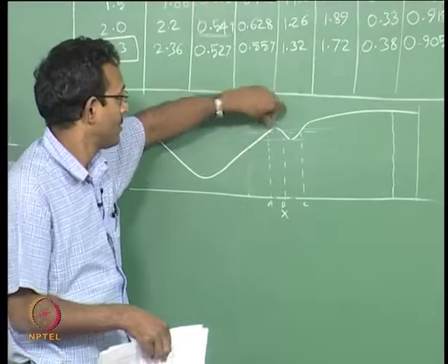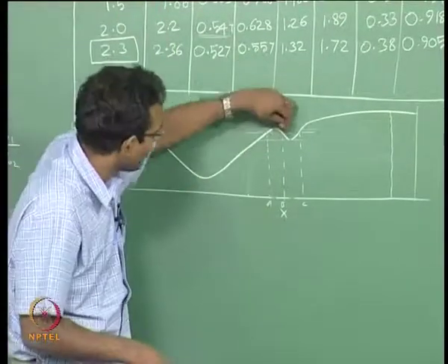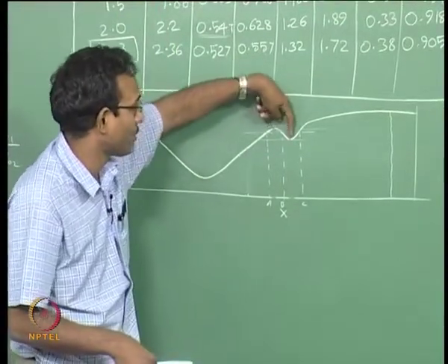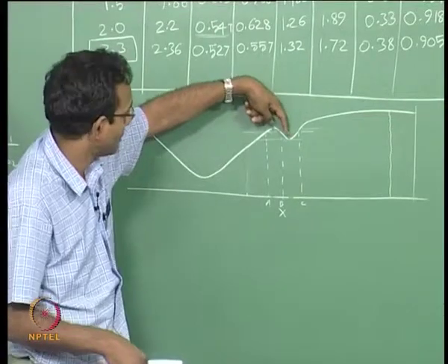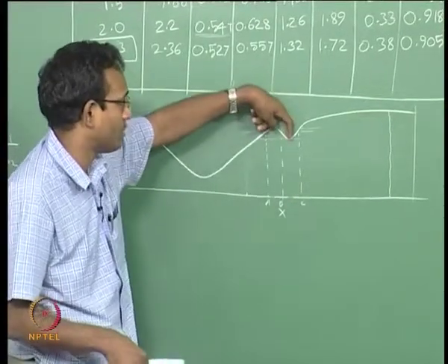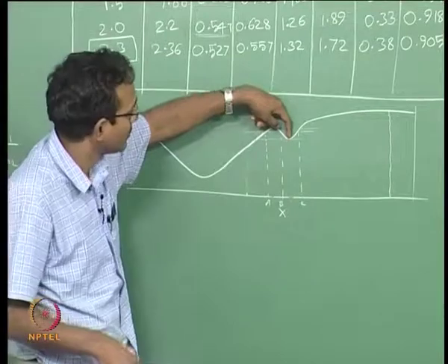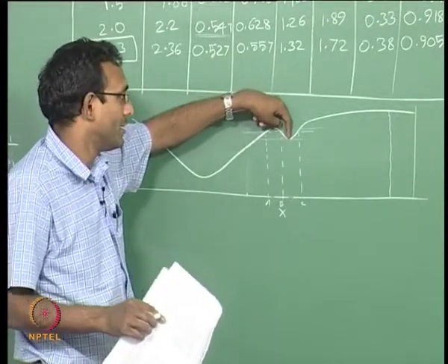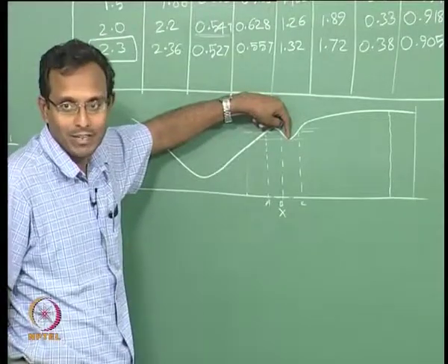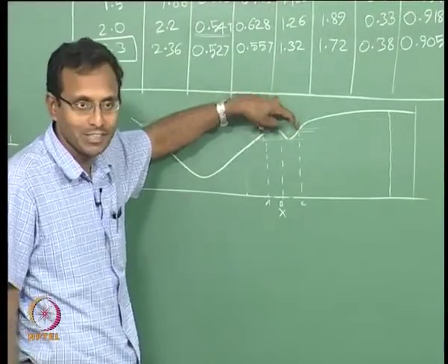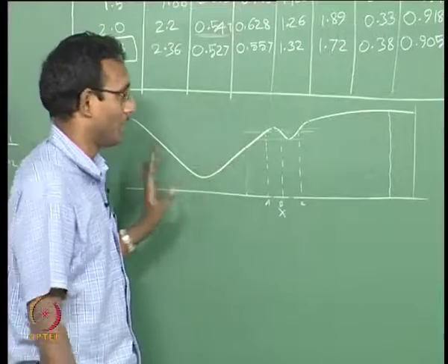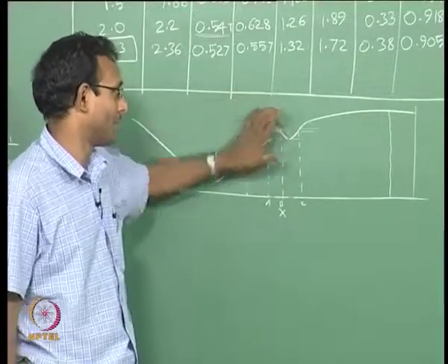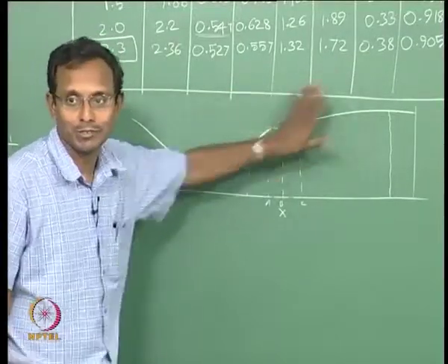If I am at this location, shock is at this vertical line, the minimum of the second throat, if you think about it, and I increase my P naught only, it will go to that point. You see, right? It is going to a higher area, it is more downstream. If I think about a simple convergent divergent nozzle, if I increase P naught, it goes downstream.